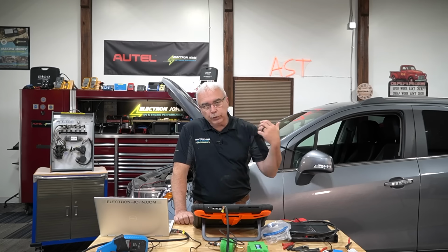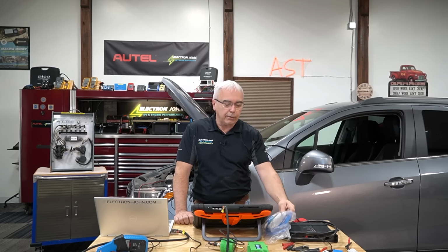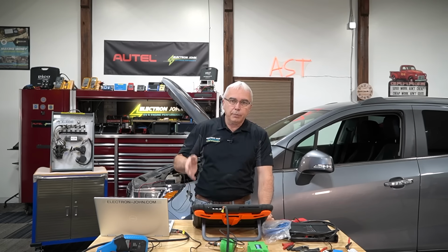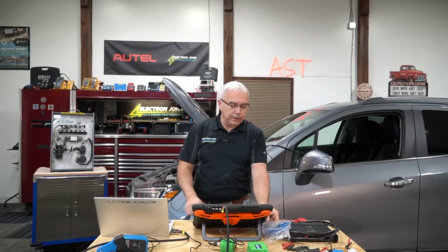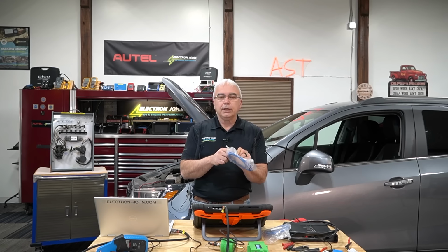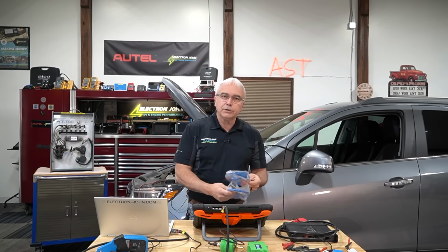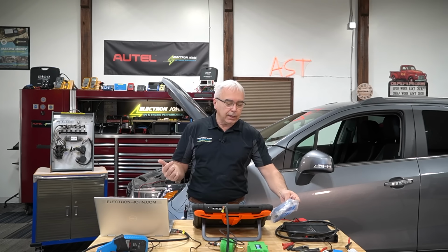But still, eventually you get to a point where, hey, does the transponder actually work in that push button on the push button start system? Well, here's a great tool for being able to figure that out. I can have my foot on the brake in park and everything and just push that button, hold the little sensor in close proximity to it, and I should get a waveform on the screen. The ultrasonic one, that's great for any type of backup alerts, right?